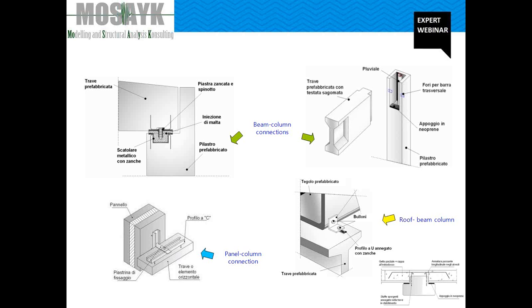In addition to this consideration, a large number of collapses have been observed in past seismic events in Turkey 1999, in Italy 2012, where several precast structures collapsed because of mechanisms related to loss of support, poor detailing of the connection, poor reinforcement,